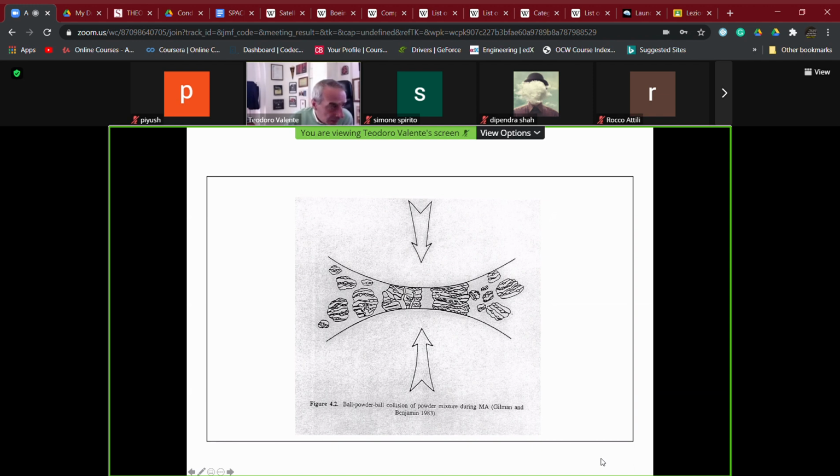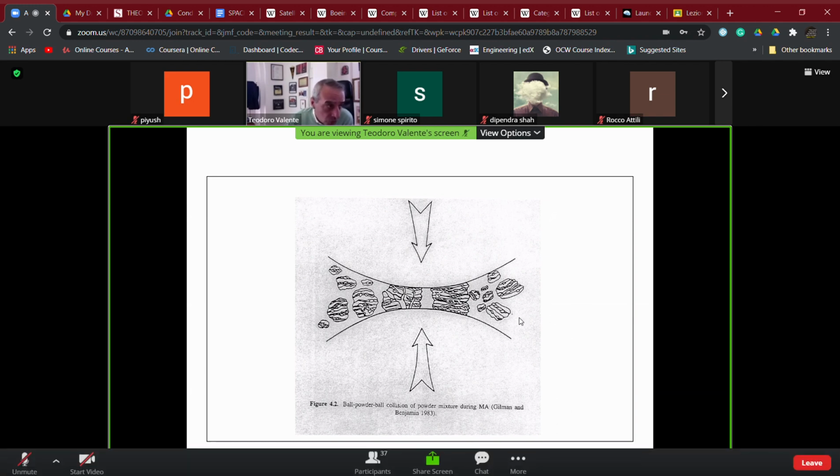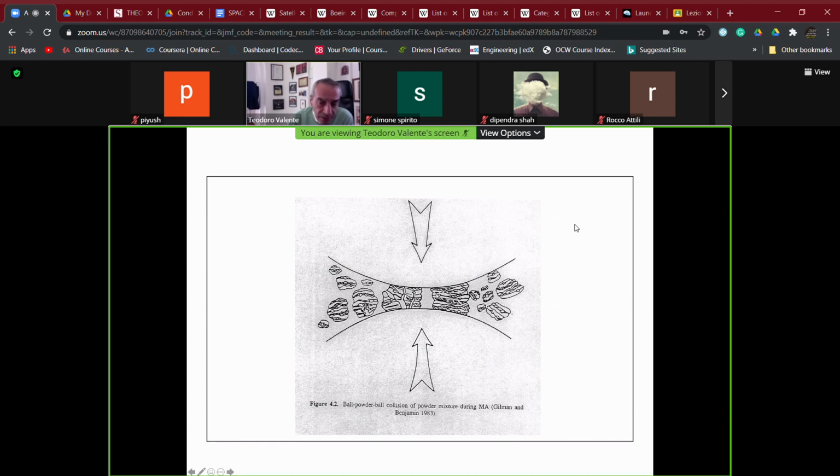So the average size does not decrease because we have reached the plateau here, but the thickness of the single layers, in the case we are going to use two different materials, is going to decrease. And so the microstructure of the final particles produced in this way, alloyed, is going to be more and more refined.